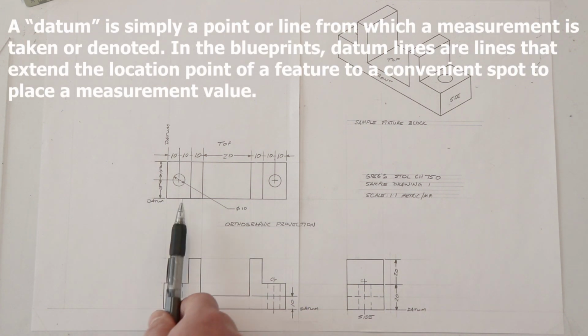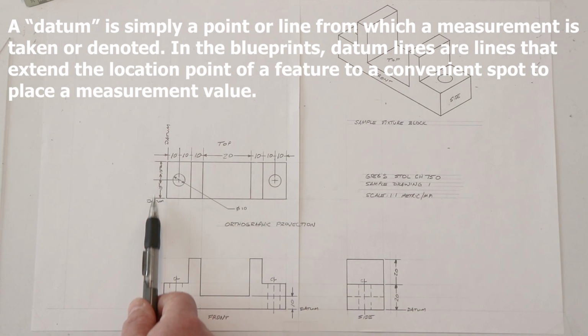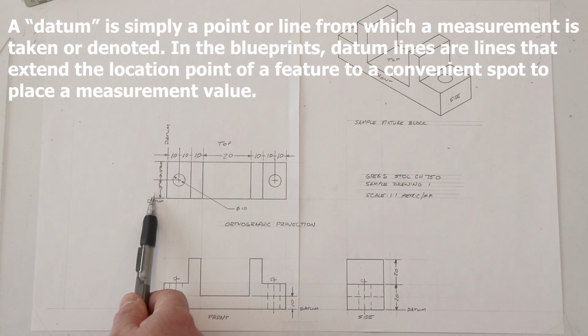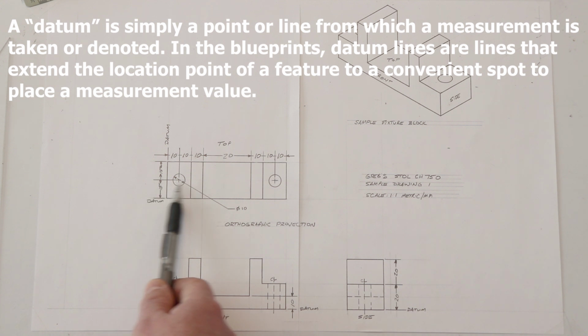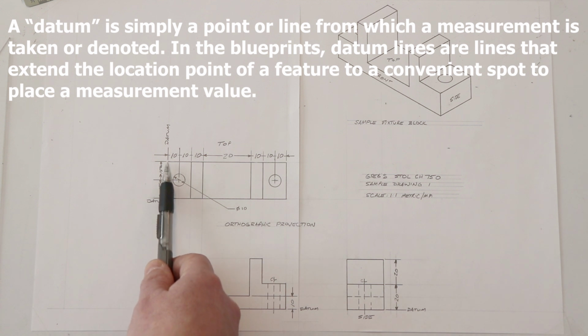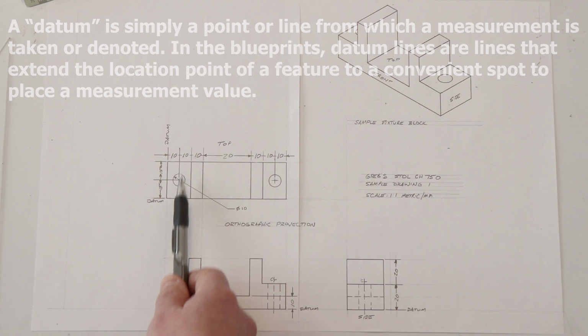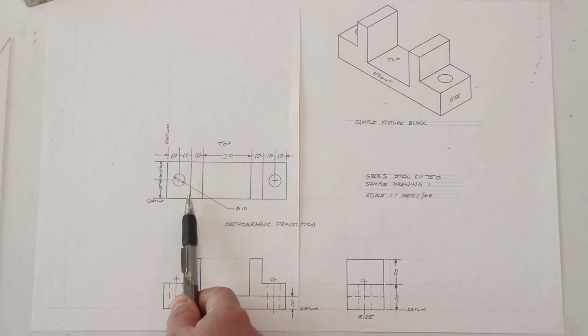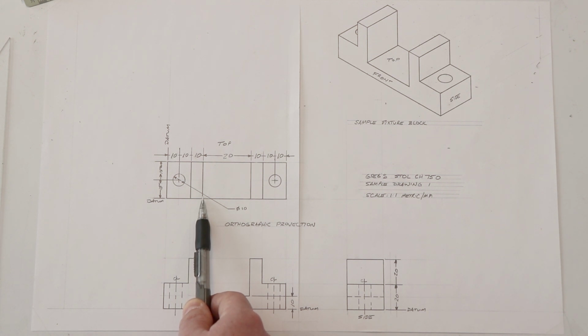I've got a couple of datum lines here that denote the dimensions of the part. Here's the solid outline of the part. We can see from this datum line that it is 15 plus 15, so it's 30 millimeters wide, which is why there's no reference line down here. We can see already right here that this is 30 millimeters wide. We know that because these are 15 and 15, the center line of this part is where these bolt holes are located. Moving up to the top datum line from left to right, we've got 10 millimeters to the center line of the hole, 10 more millimeters to the edge of this shoulder right here. Then that shoulder is 10 millimeters thick.